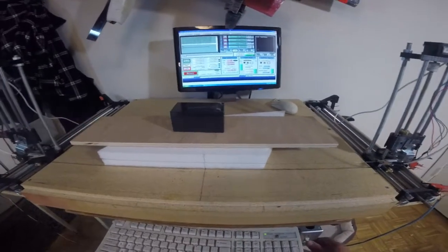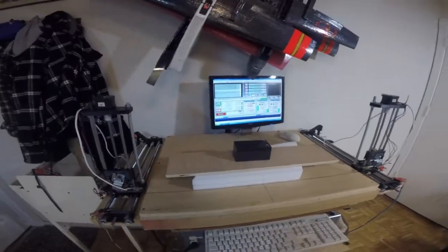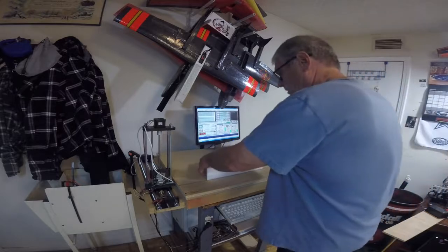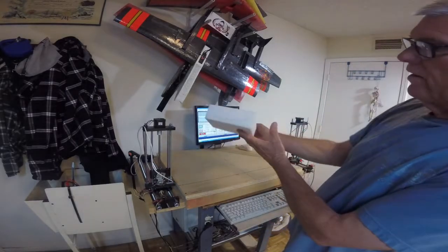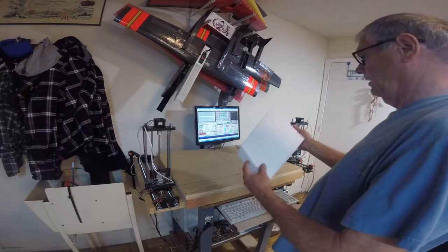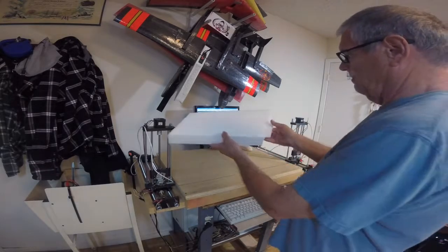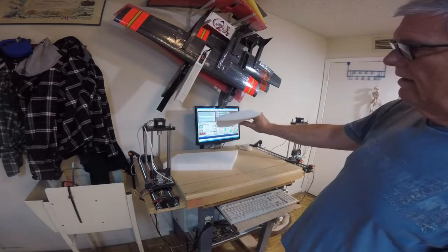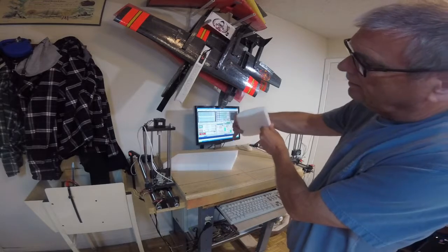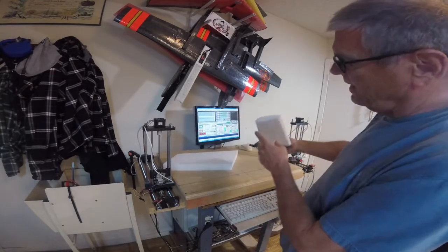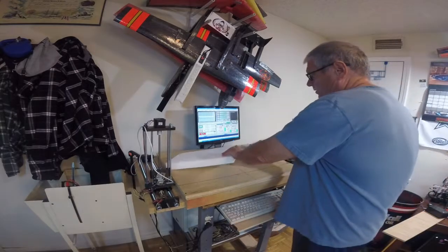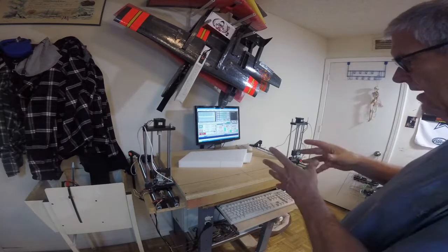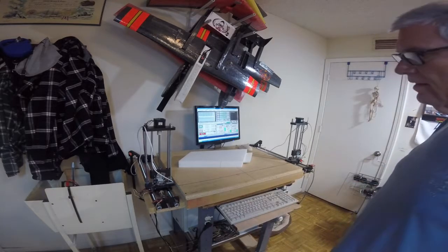And as that wire exits, we'll reach down and we will turn the wire off. And take the weights off of it. Now we have our core cut. It's a matter of pulling it right up here. And we have our wing core cut. This actually has about 1 degree of washout that's cut into that wing core. And that's basically how it's done. Cut 2 halves. There's a different kind of setup for the center section. And glue it together.